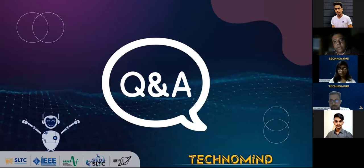Now, if I showed you that TurtleBot, for example, that TurtleBot runs using a Raspberry Pi, right? So if you use the real robot, you have to develop the software on the Raspberry Pi and execute it. Instead of doing that, you can write your software and run it as a node on your computer, on any kind of PC, and execute it on Gazebo and see whether the robot is working well. And after that, you can actually execute it on the robot. So I can recommend that, thinking of the tasks that you are going to do. You don't need development boards if you do that. Actually, that's why we have those simulators.